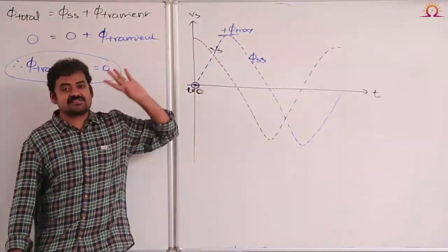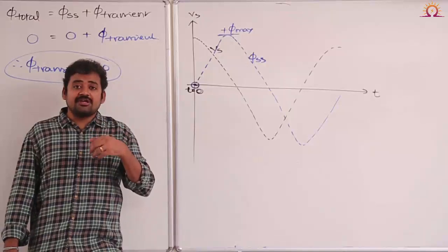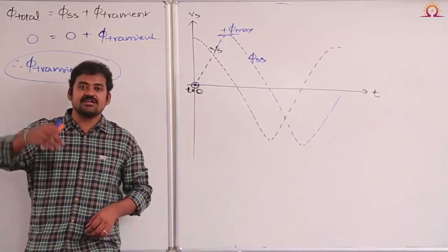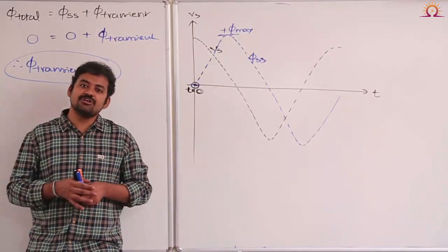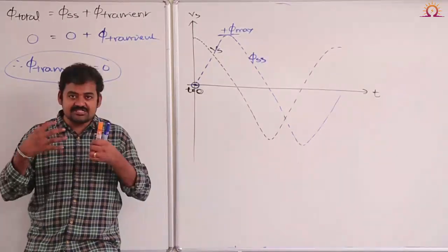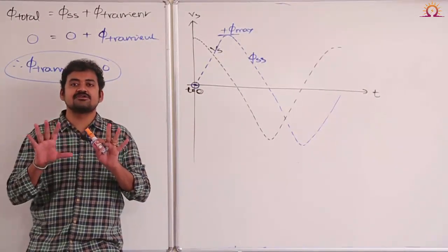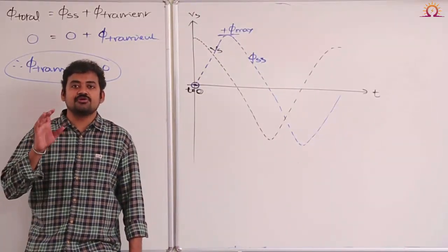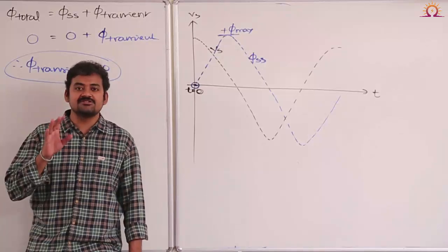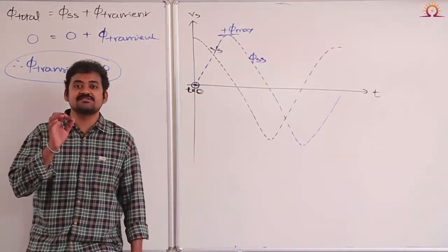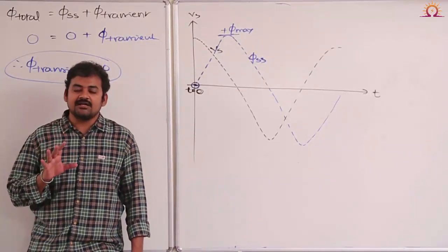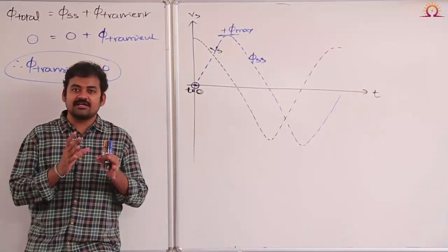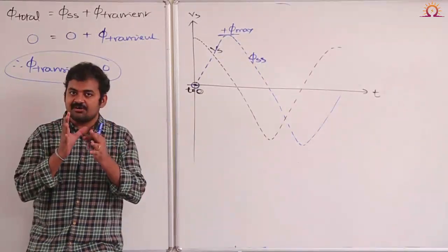Supply voltage is maximum. But you cannot give a guarantee about it because the supply voltage is continuously changing. It is a time varying value. So we have to design the transformer to withstand magnetic inrush currents always. Magnetic inrush currents are produced when you try to switch on a transformer at an instant where the supply voltage is crossing its 0 value. And you tell me, is magnetic inrush current only steady state current, or only transient, or the sum of the two? Yes, the sum of the two.